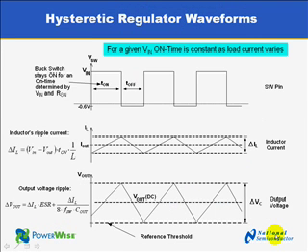So we just learned that a standard constant on-time regulator needs a sufficient ripple at the output. How can we influence that ripple? Let's look at the buck regulator waveforms and the mathematical formulas. The first row on this slide shows the waveform at the switching pin. The second one shows the current in the inductor, and the third one the ripple of the output voltage, which is the one that's mostly interesting for us.